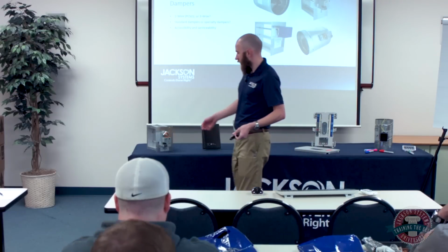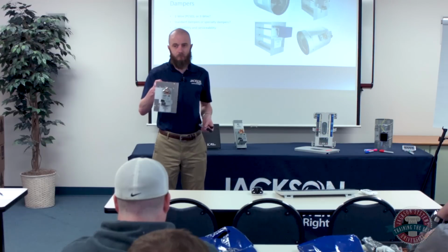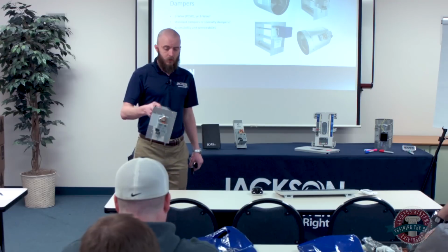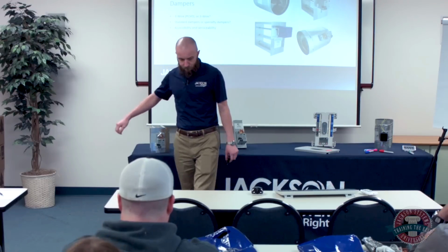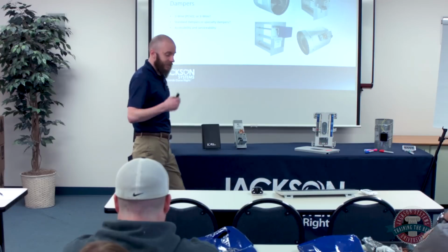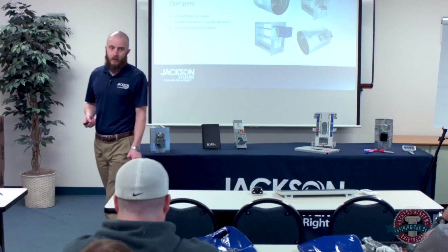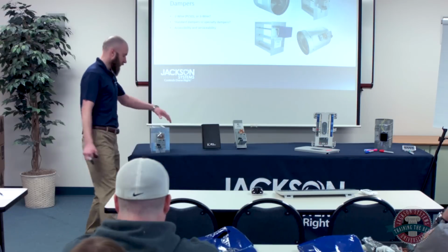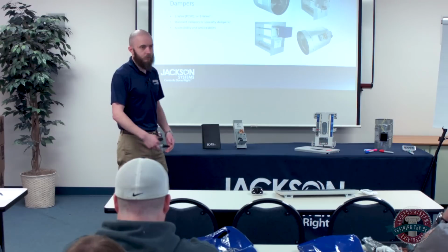Other dampers, like these with the Belimo actuators, the 3-wire actuators only pull 2.5 VA. So you can put a lot more of these on a 40 VA transformer before you run into trouble. These are really efficient actuators, so that's something to consider. Keep an eye on how many dampers you're putting on the system and how much VA they each draw to make sure you're not going to overload your transformer. If you need to, you could either shift to a lower VA rated damper or increase the size of your transformer.